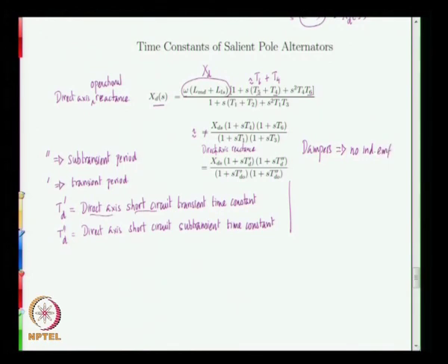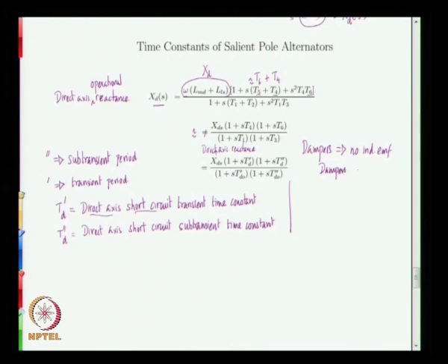If there is no induced EMF, there are no eddy currents flowing, and therefore as far as the equivalent circuit is concerned, the dampers may be looked at as an open circuit, which means the damper does not really exist in the equivalent circuit. That branch is simply neglected.